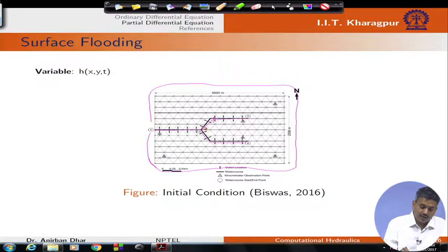And obviously, in this case, this is your junction condition position, this is your inlet condition, this is our outlet conditions. So, at these 3 locations we need to specify the boundary conditions or external boundary conditions, and for this internal node we need to specify the internal boundary conditions.